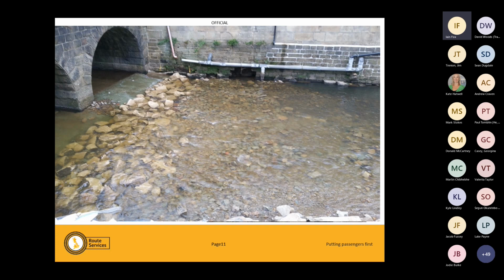Drainage systems produce scour. We've put this in a concrete channel. However, you can see some scour and undermining of the wall there. It's moving water. It's what it does. Poorly designed culvert. I love this picture. It's not a Network Rail one. I don't know whether this is the upstream or the downstream. I have a feeling it's the upstream end of a farm crossing or something. This gate's a little bit worrying because it's a Network Rail colour, but there we go.